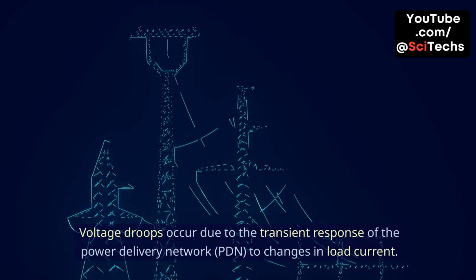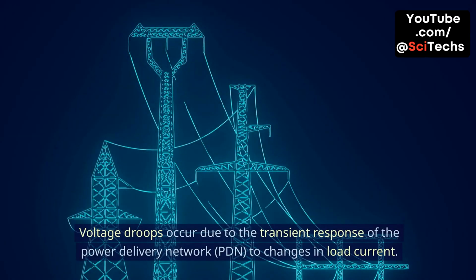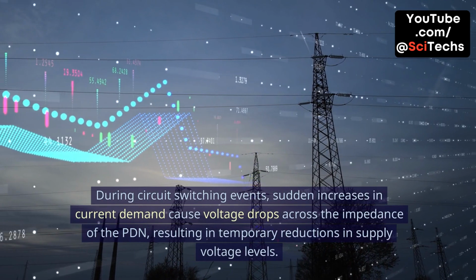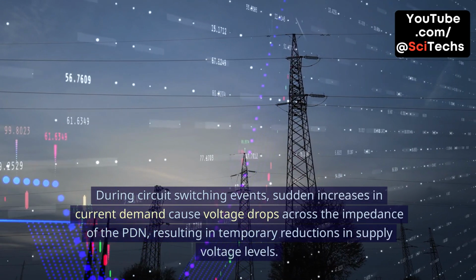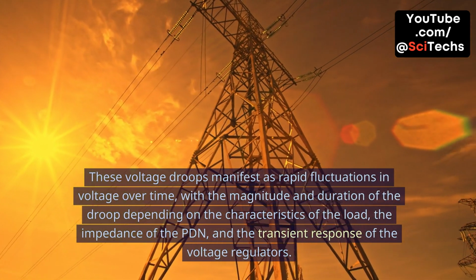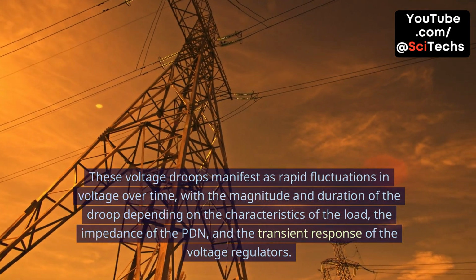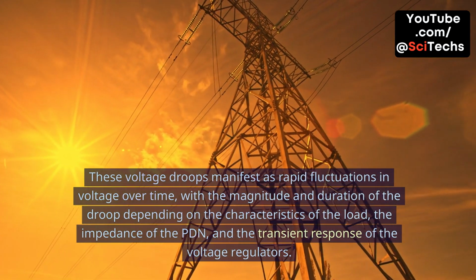Voltage droops occur due to the transient response of the power delivery network, PDN, to changes in load current. During circuit switching events, sudden increases in current demand cause voltage drops across the impedance of the PDN, resulting in temporary reductions in supply voltage levels. These voltage droops manifest as rapid fluctuations in voltage over time, with the magnitude and duration of the droop depending on the characteristics of the load, the impedance of the PDN, and the transient response of the voltage regulators.